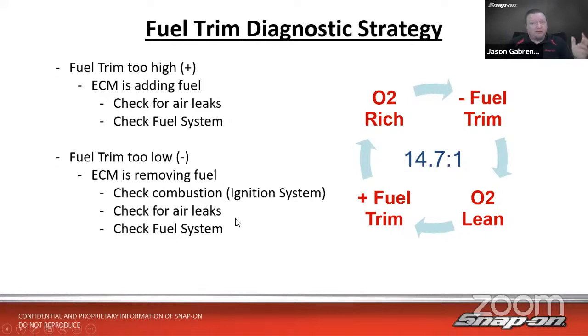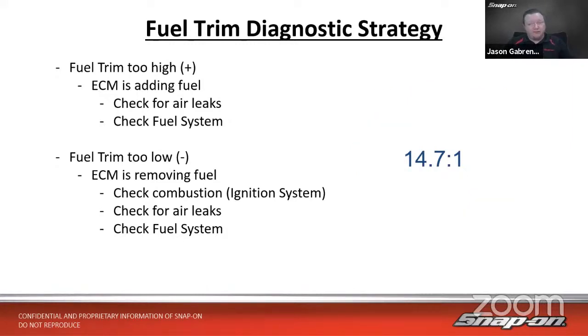Certain vehicles, especially turbo vehicles, if I have a leak after my metered air, somewhere in the boot or in the intercooler maybe, if I have an air leak and I go under boost, that is metered air that's getting out. So it's not getting as much air as it metered, so it's going to run rich. And then check the fuel system once again. Make sure I don't have a high pressure situation, leaky fuel injector, something of that nature, right? So we want to check, is it too high or is it too low?